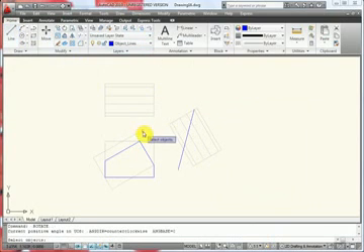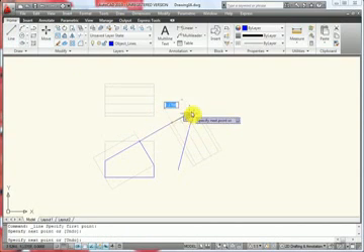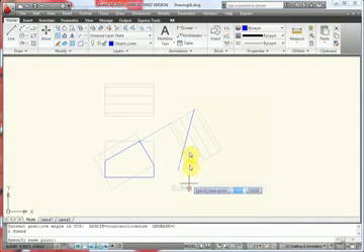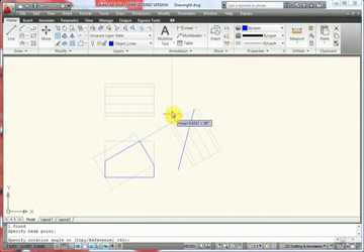I'm going to repeat that with the space bar. I'm going to repeat the line command, that is, and choose the point on the front view here, and then choose the other offset line I drew, and exit that with the space bar. I'm going to choose that line one more time, and right-click in the graphics window and choose Rotate. Now I'm going to choose a pivot point, which is the intersection of this offset line and the outside of the rectangle. And I want to have this back at 45 degrees as well. However, I have to go past 90 and then 45, which would actually be 135 degrees.